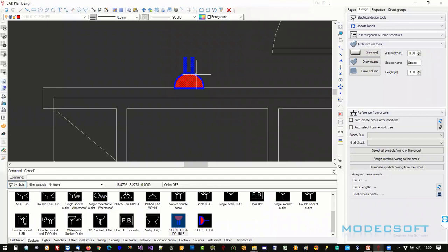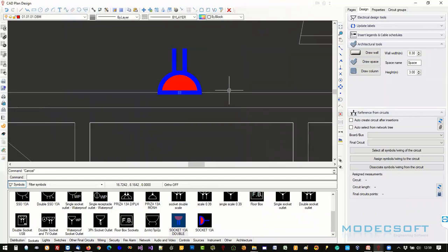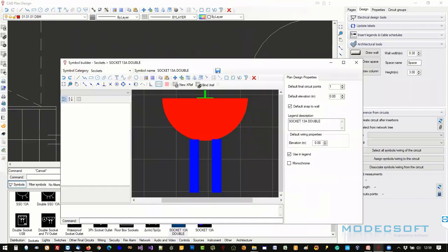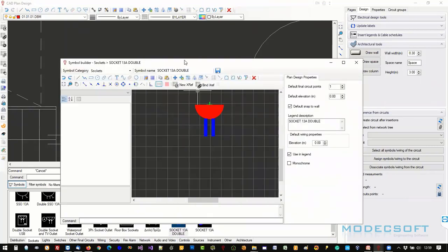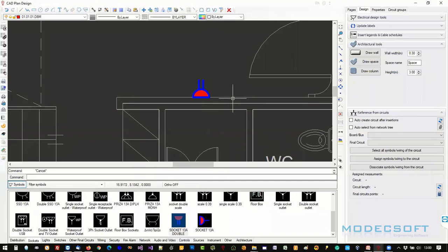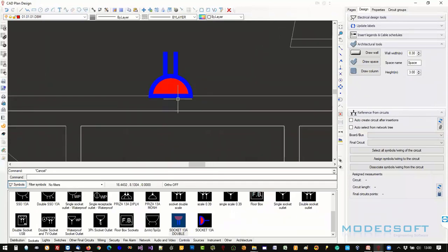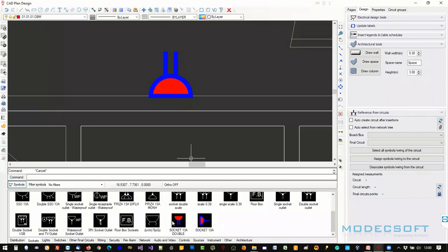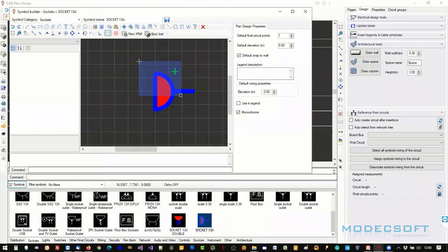And you see the colors that are presented there. So that's one thing we should notice: the symbols should have this orientation, either from top or bottom, at the insertion point, if you want to align them to the wall. Don't have them vertical, because the maths that we are doing to get the right positioning assume that you have them all placed horizontally like that. So it's just a way. Yeah, hopefully that answers your question.